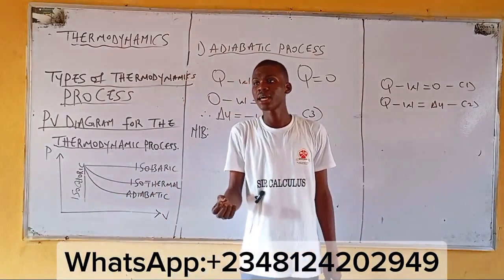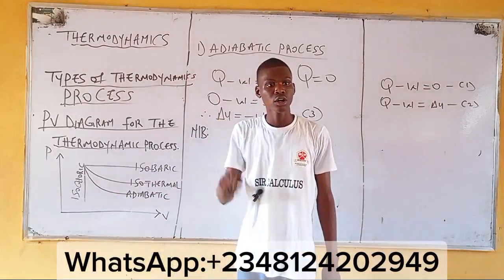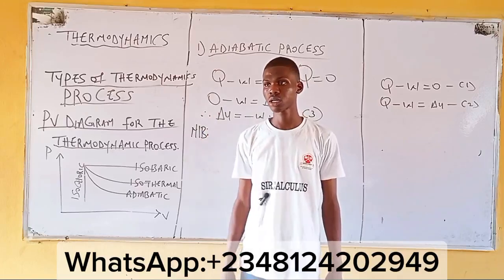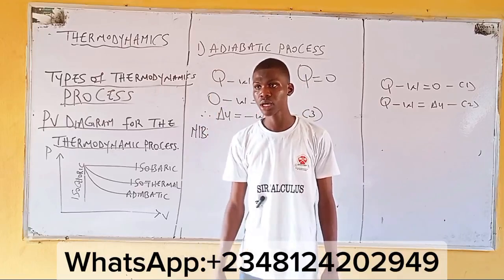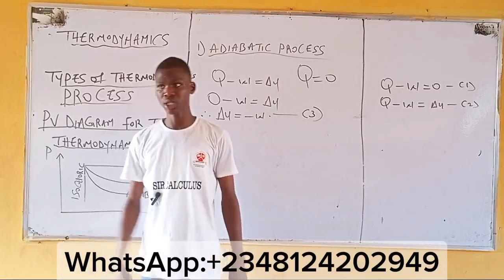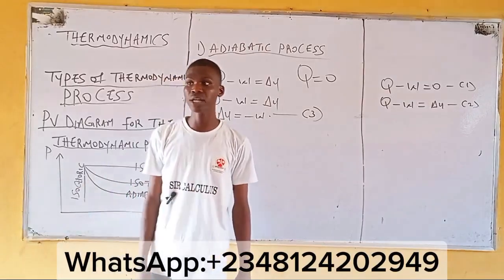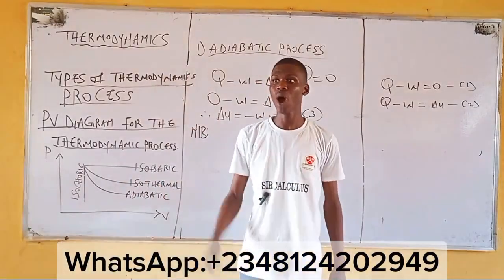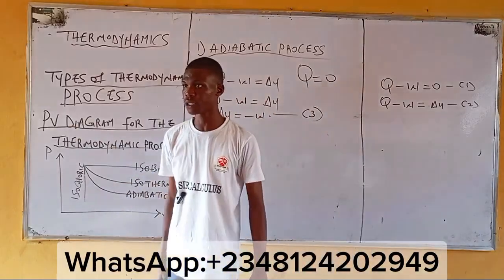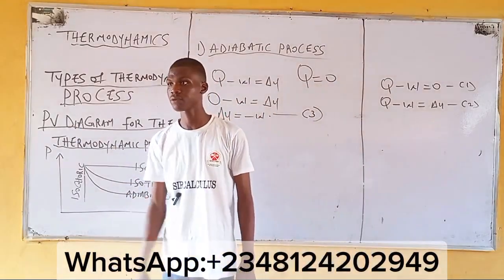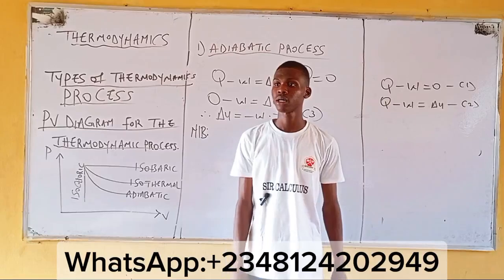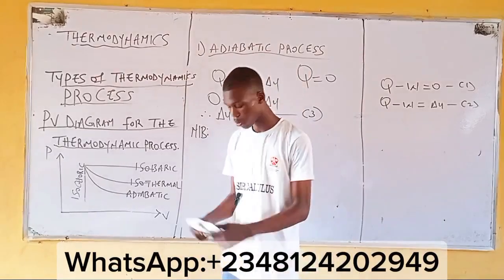Now, go back to sign convention. Number 2 sign convention is: when a fluid pushes a piston outward, the work done is positive. The word is expand. Now apply that here too. When your system expands adiabatically, what will your work done be? Positive. Exactly. So vice versa, when it compresses adiabatically, your work done will be negative.